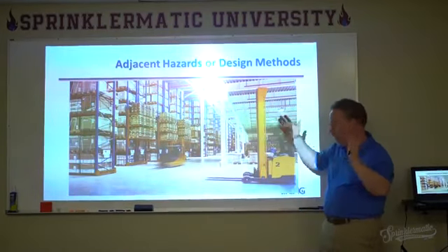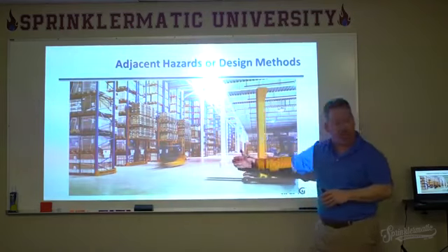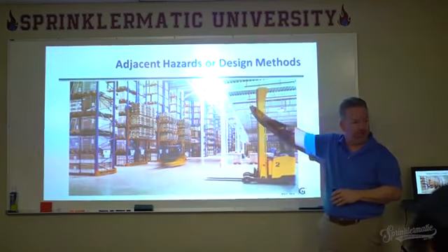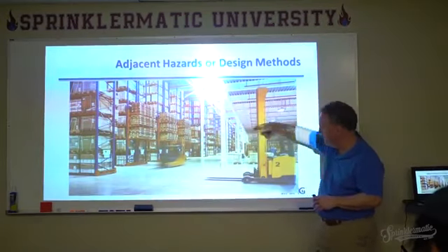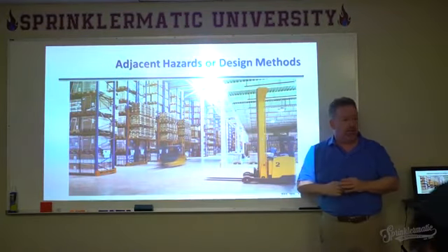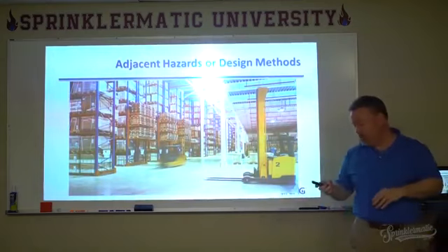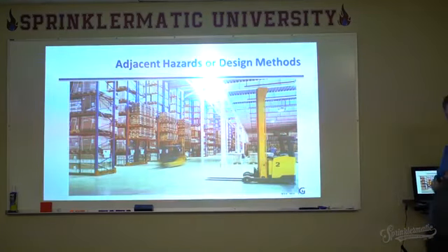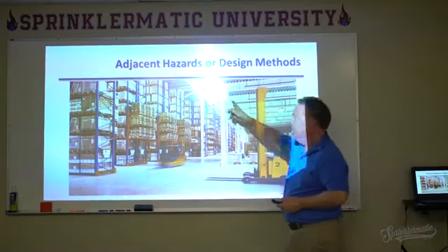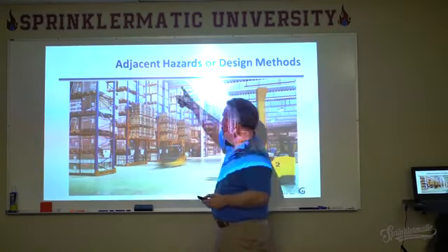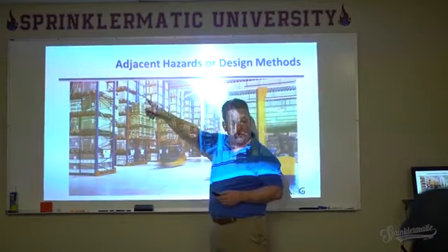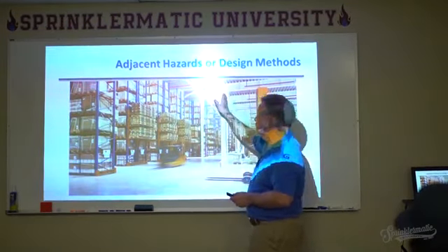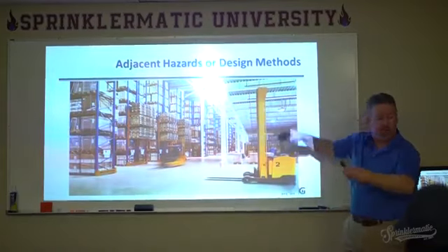All right, so we've got a requirement for a separation here, an aisle separation, and a draft curtain, or a separation in the ceiling height. And then we can have these two design areas close to each other. And that's the only time you can use draft curtains. You couldn't use draft curtains if this is an ESFR sprinkler system out here, which most likely is. You can't have draft curtains out within this design area, but you could have a draft curtain separating the two design areas.